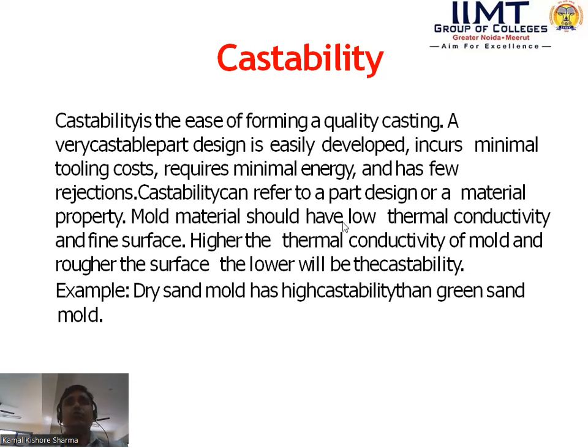Mold material should have low thermal conductivity and a fine surface. The higher the thermal conductivity of the mold and the rougher the surface, the lower the castability. Dry sand molds have higher castability than green sand molds.